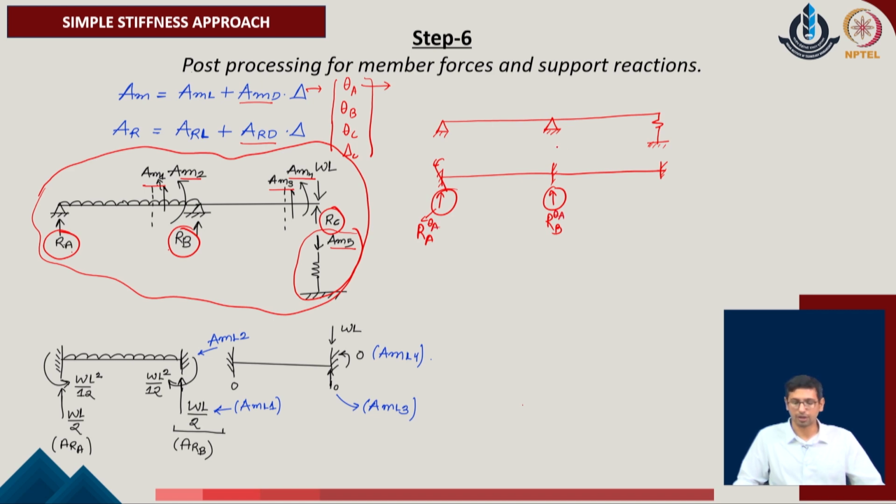In the same manner, one can come ahead with the second parameter where the rotation at theta B will be evaluated, and corresponding to that theta B rotation, again we will evaluate these system reactions, and they will become the system reaction at the point A and the point B with respect to the rotation of theta B in the given system. Similarly, we can do this for the remaining other 2 degrees of freedom also of the given problem.